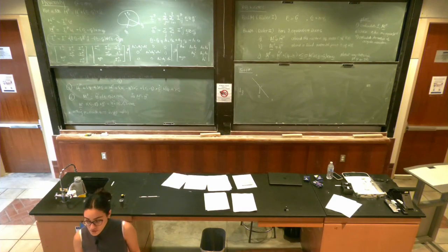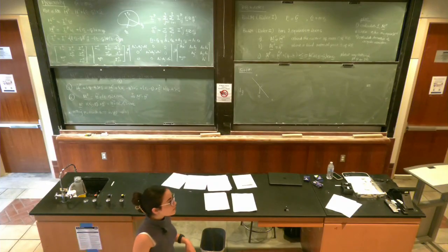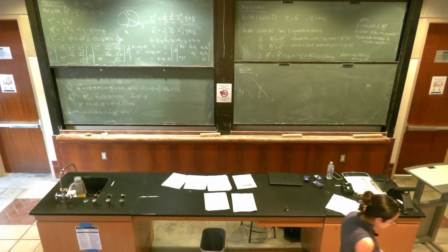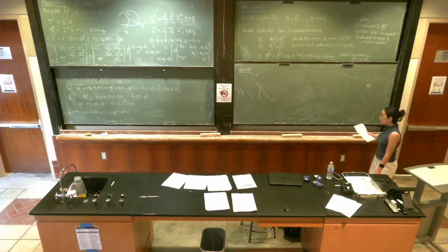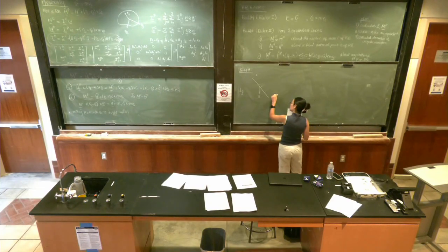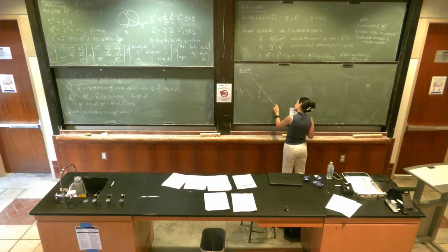Any other forces acting on the bar? Normals at where and where? A and B. So I have to be careful at B, because the seat is kind of inclined. 7 degrees was the horizontal. So maybe I'll draw it as a dashed line. So I'm going to have a normal force that's slightly inclined.